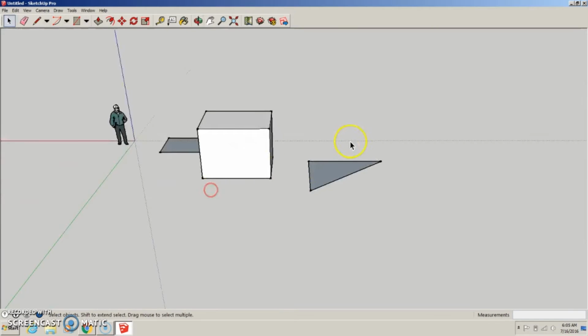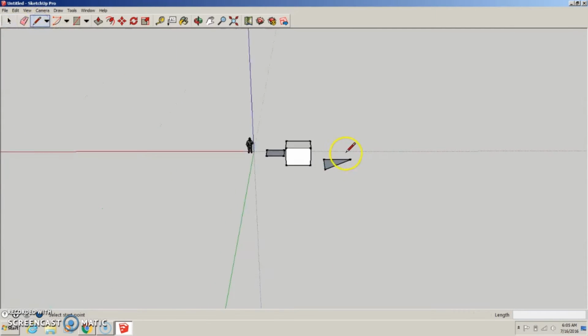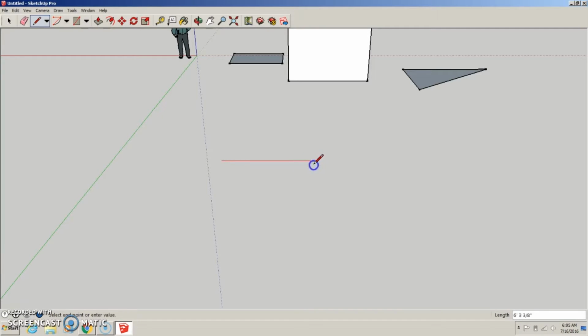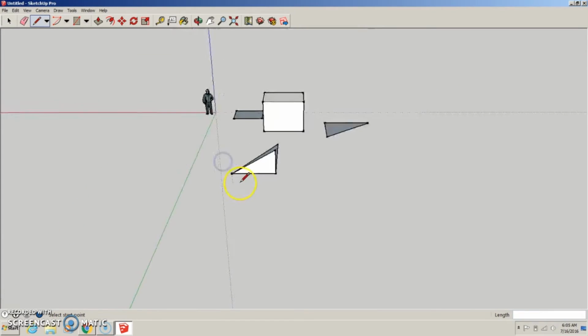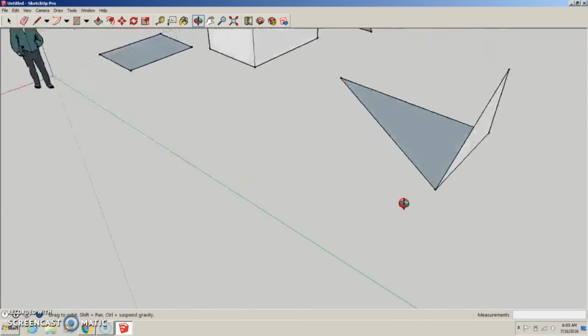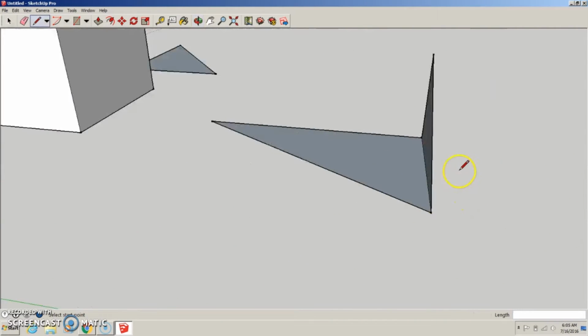The biggest tip I can probably give you about drawing with single lines is to keep your lines parallel and perpendicular with each other to create surfaces. Now you notice as I'm dragging here, I have the left mouse pushed down. I have a green axis, and if I adjust it a little bit, it turns to blue. Now I'm going up and down. Here I'm going along. So I can draw that line in. I'll show you. And I'm going to try to get that to come up in the blue and connect them up. Hold down the scroll, and there it is. Let's see what I drew.